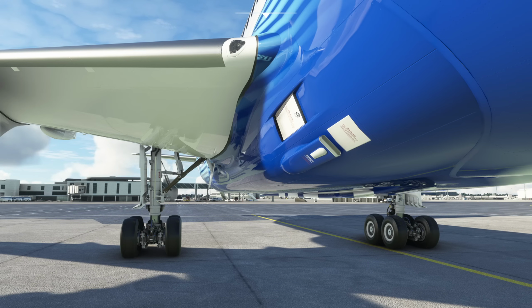The air conditioning pack uses this door. This is the ram air door for the packs. This air goes in, it then goes over the air conditioning pack, and it's used to cool the air that we've taken from the cabin air compressors. It's used to cool the air, and then this air is actually vented overboard again.